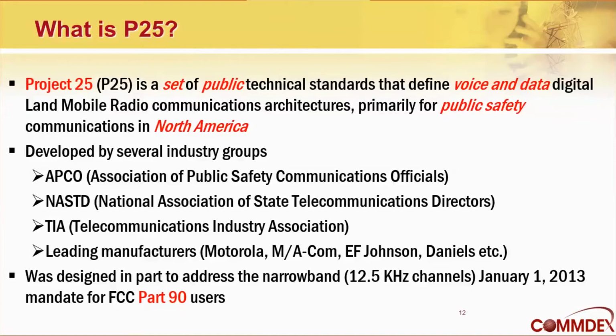So the VHF marine channels are still 25 kilohertz. And also the amateur radio service in their 2-meter and 440 bands still can operate in 25 kilohertz bandwidth. But all the Part 90 users, which includes public safety and commercial users, had to go narrowband in 2013, which drove the need for P25.